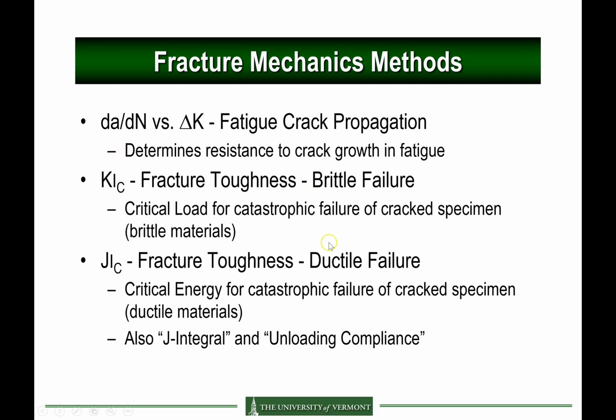So if your material really exhibits a lot of ductility, especially if it is tested at high temperature, then in that case we will use another technique called the J1C analysis, which is based on the J integral theory. There is a relationship between J1C and K1C. But the protocol is a little bit more complicated, and so we're not going to do this in lab number 6.